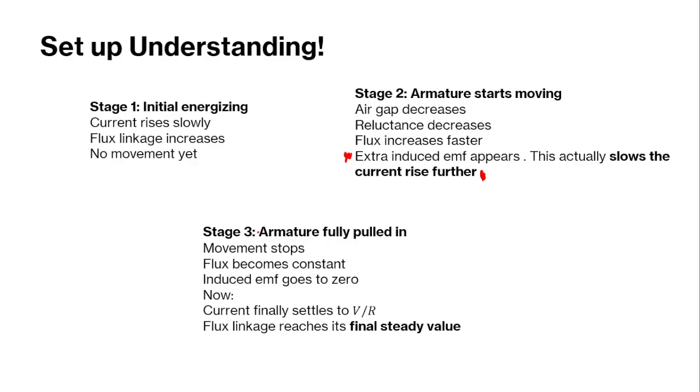And the last stage: it will just keep moving until the armature is fully pulled in. When that happens, the movement stops, obviously. The flux becomes constant because, remember, it's basically just a core material now. It has no more air gap.